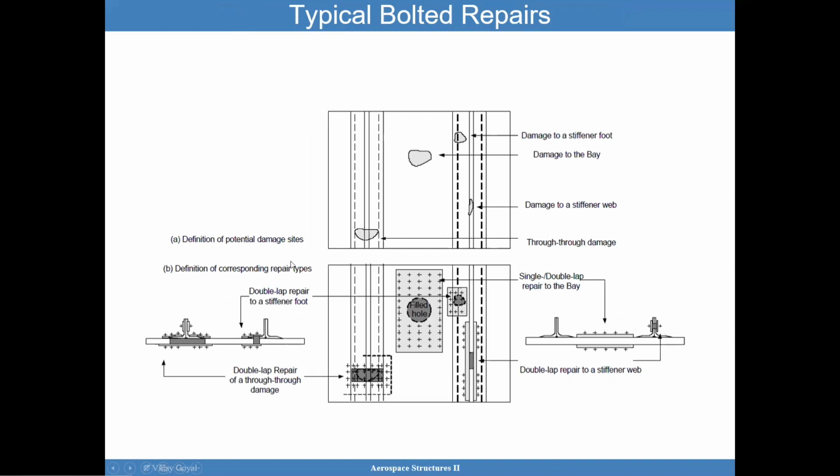The definition of potential damage sites is important. The definition of corresponding repair types is important. Here you can see a doubler lap repair to a stiffener foot in this area. And then here's a doubler lap repair through a damage, as you can see here. So it's important to apply doubler repair procedures whenever required.